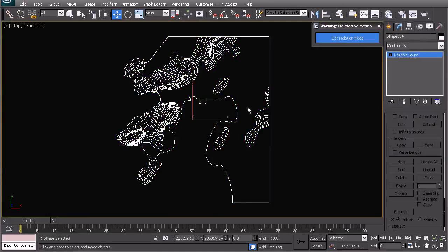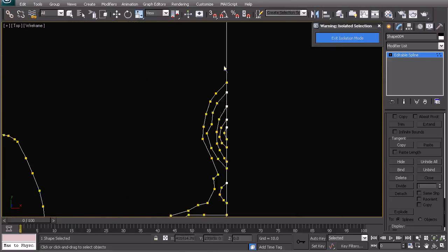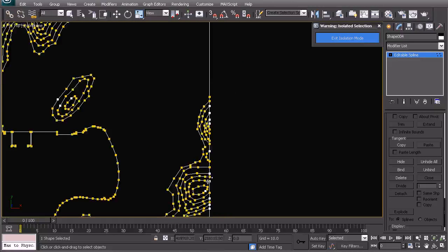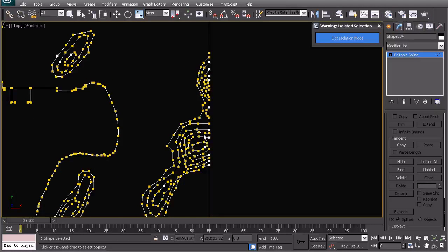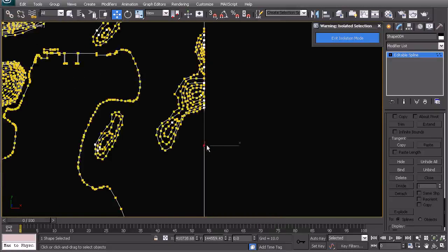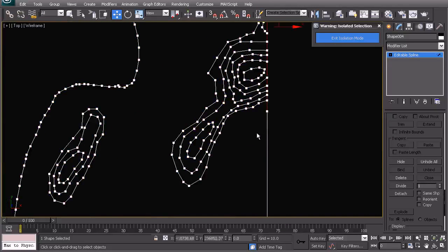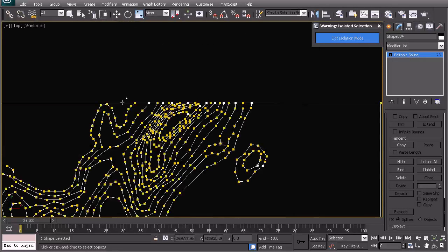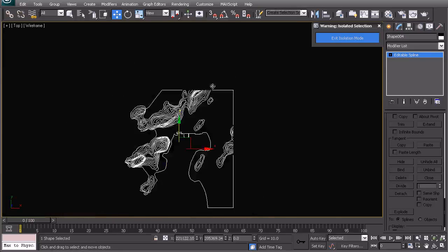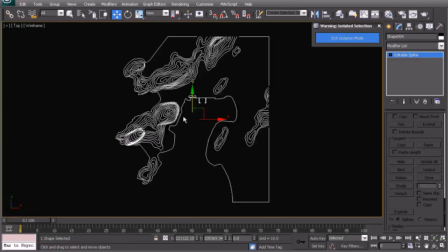And I'm also going to refine the edges a little bit so that we do not have the confusion of the line basically on the side here, which is saying 0, and right next to it we have, let's say, 200 meters. So that doesn't really work. So we will just do some editing here, create some vertices that we will then use to delete these lines. Just refine that as well. Maybe here and here, and then we will delete that part. So what we have now is the whole set of splines that are ready for the terrain tool.